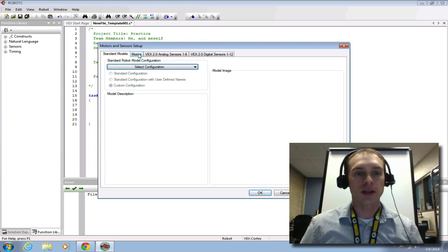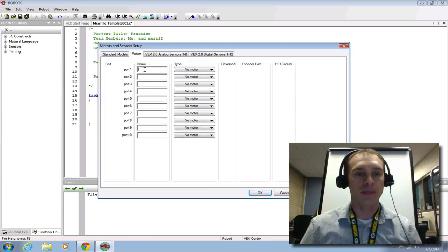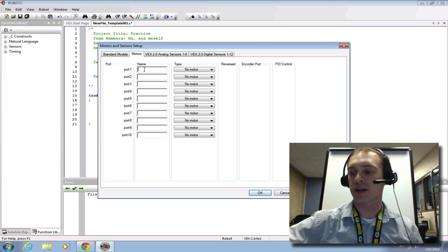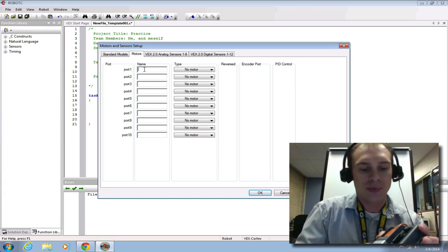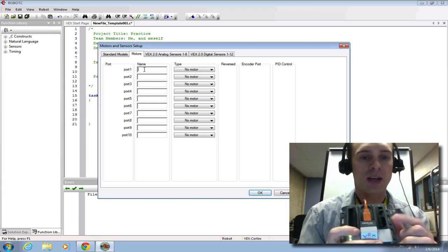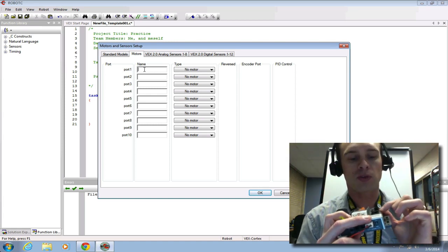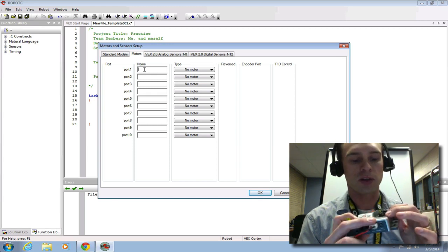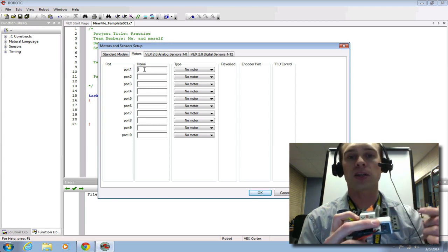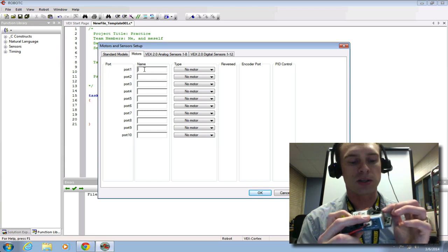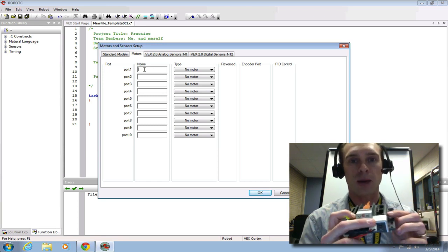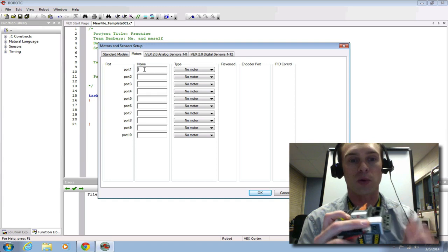Now generally you will click on the Motors tab, and port 1 of your Cortex in the Motors tab is right here, and you can read the word motor on this, and you have ports 1 through 10. Port 1 and 10 look slightly different than the others. They are only 2-prong. So if you're plugging in actual motors using the motor controller wires, it's 2 through 9 are your options. Generally, the flashlight goes in number 1.